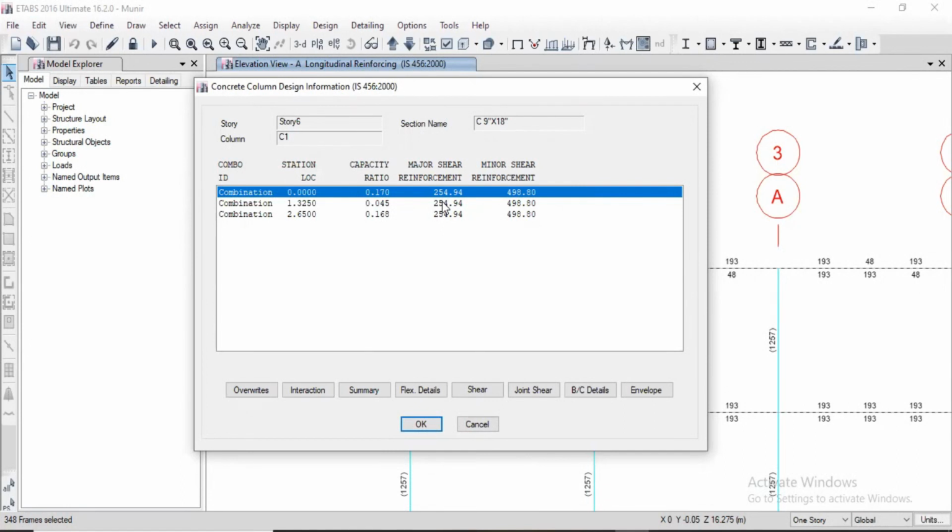I think the outer and internal. Major reinforcement and minor reinforcement is basically when we provide the steel. We have provided 16 mm bars at the corner, so in that case the area will be increased there, and in the middle we have provided 12 mm bars, so in that case the area will be reduced there. So that is the major and minor reinforcement.